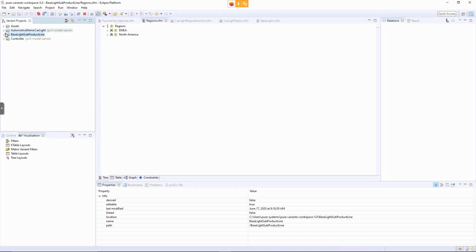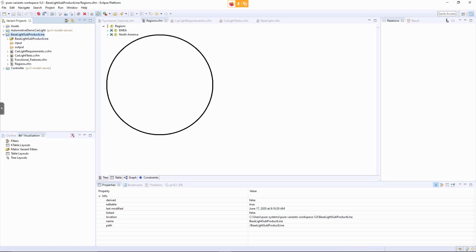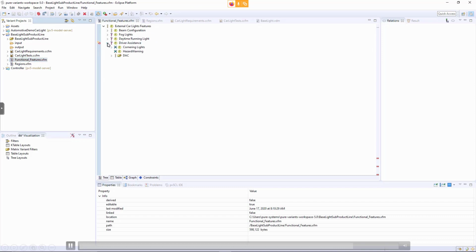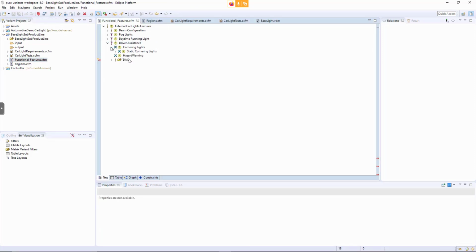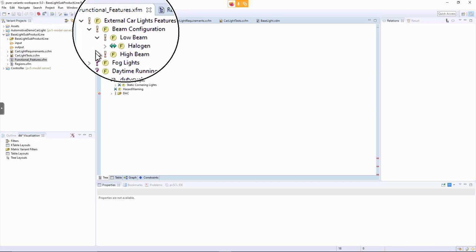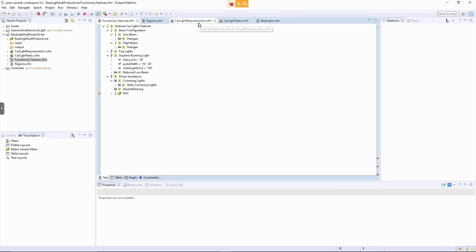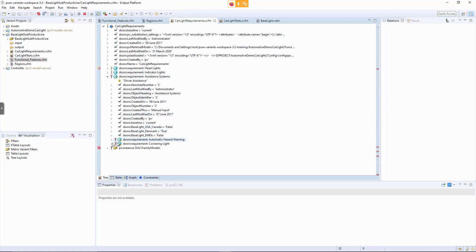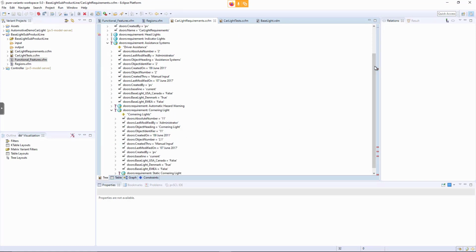So basically, based on this VRM, pure::variants will for this subproject create the according feature models, which are actually kind of 120% feature models of the feature model that we saw earlier in our 150% project. So you see here, for example, the feature Xenon doesn't show up in that feature model, as we earlier decided this is not part of the subproduct line, as well as all other excluded features.